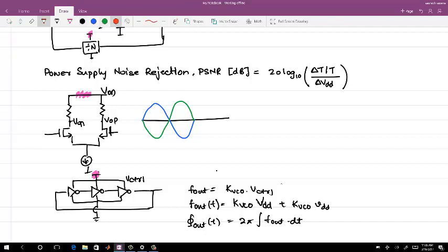If I change the common mode because of the change in the supply, I am riding on this. If you look at the signal swing, it is still differential, so these swings are not going to change. If you are thinking that this is changing with respect to common, no, that is not the case here. That will not cause any trouble as such.